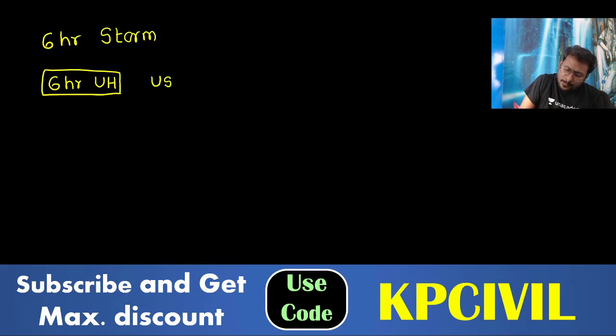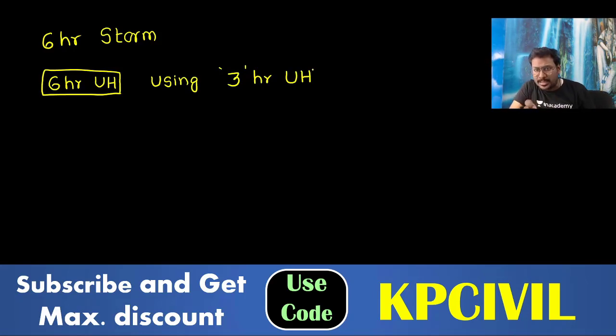This is the 3 hour unit hydrograph data provided. For example, a 6 hour storm occurred. So plot the 6 hour unit hydrograph using the given 3 hour unit hydrograph.